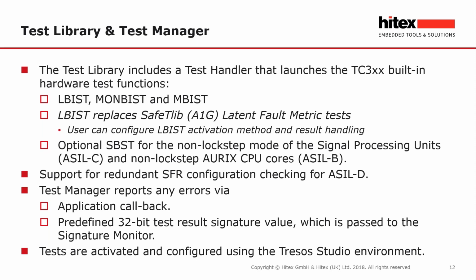The SBST is a piece of software which is provided by Infineon and which is separate to the SafeTpack. So the SafeTpack provides the interfaces to the software, but the software has to be obtained separately. There's also support for redundant SFR checking. So those familiar with the SafetyLib will remember the SFR, CRC, and SFR comparison tests. These are required for ASIL-D.